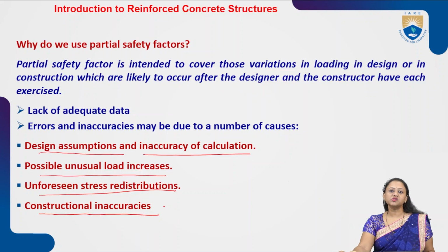So the purpose of introducing the partial factor of safety is that we need to find a way to fill the gap between these inaccuracies in calculations and inaccuracies in construction practices, as well as the assumptions that we are taking for design purposes.